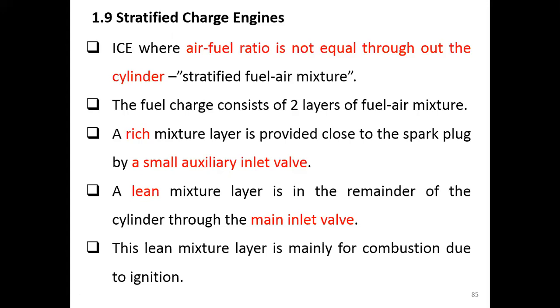Let's see how the engine responds if, instead of providing a homogeneous or uniform charge, we provide the charge as non-homogeneous. An internal combustion engine where the air-fuel ratio is not equal throughout the cylinder, we call it a stratified fuel-air mixture.